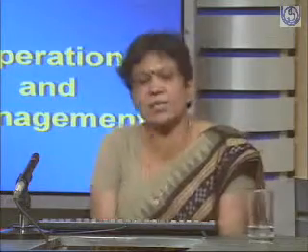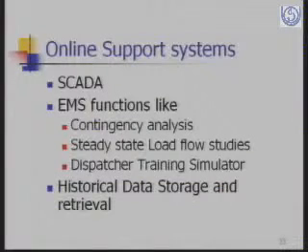The online support systems for dealing with grid management are, first, we need a good SCADA system. SCADA means supervisory control and data acquisition system, which means that we have RTUs, remote terminal units, installed at all the substations, which through a communication system send data regarding various parameters, voltage, power, energy flows, current, power factor, etc. to the load dispatch centers, and we have data of all the substations and transmission lines at a central place.